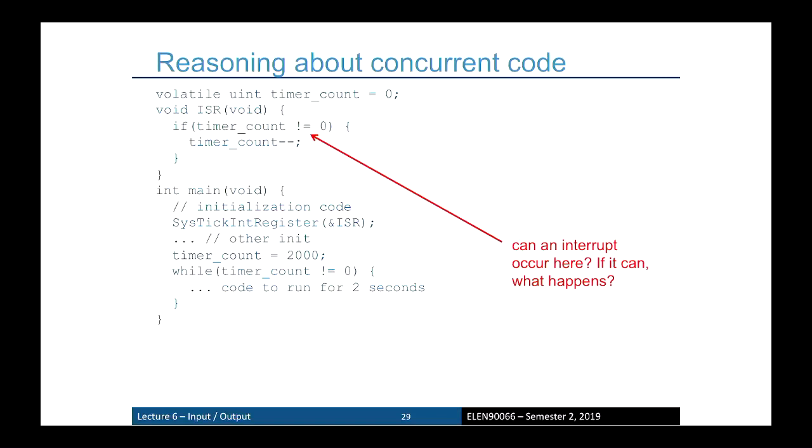So what we typically do is, when an interrupt's called, so a piece of code's running, an interrupt happens, and it jumps up here, we disable interrupts from happening. We don't want interrupts to happen while we're still decrementing a counter, or before we've got to decrementing the counter and another interrupt comes in.